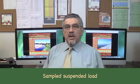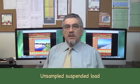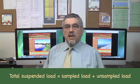The term sample suspended load is used to describe the fraction of suspended load that is possible to sample with available equipment. It excludes the unsampled suspended load, that is, the fraction of suspended load that is carried too close to the stream bed to be effectively sampled. The sum of sampled and unsampled suspended loads is the total suspended load.